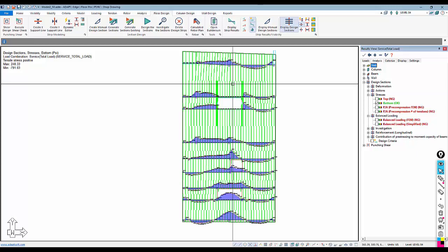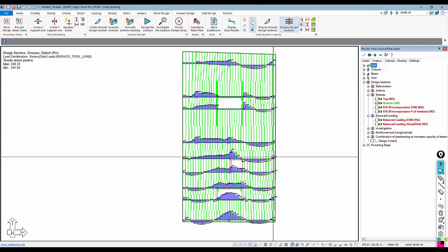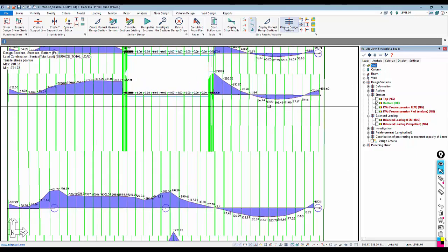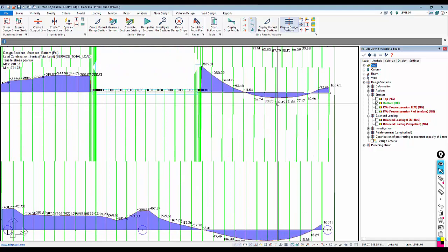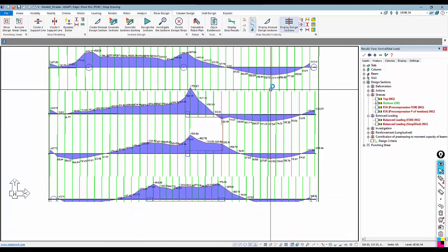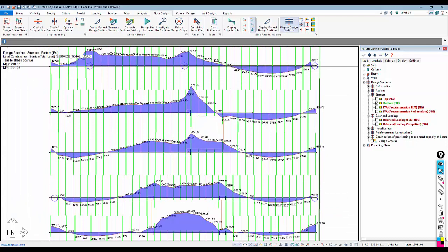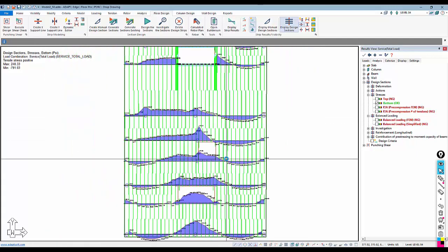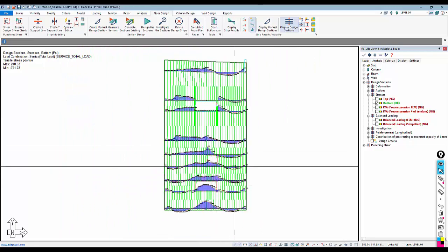The allowable based on 5,000 psi concrete strength is 424 psi, and that's in tension. And you can see we have tension here. Positive is a tensile value. Maximum we have a tension of 240, which is far below 424. So the slab in this direction is acceptable from that bottom stress perspective.